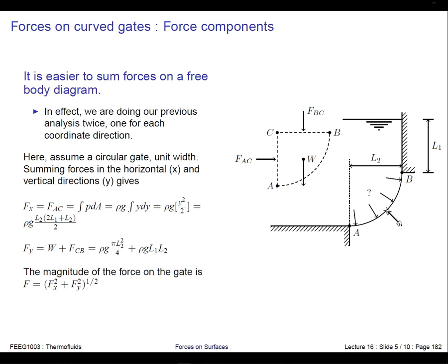And then we can work out the force in the Y direction. So this is the Y component of this resultant force that we're trying to find, and we've got two forces that are relevant. We've got the weight of the fluid and the force acting on this surface.